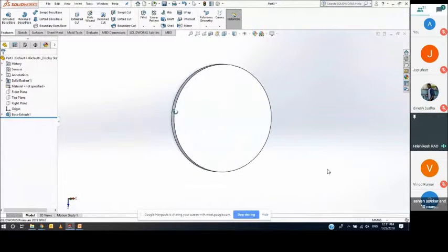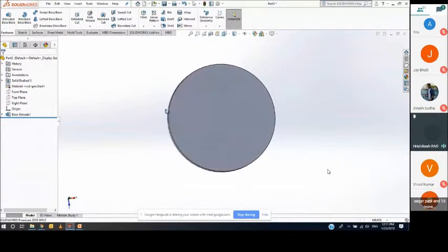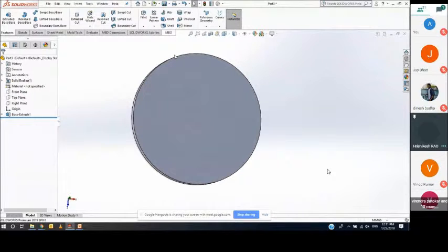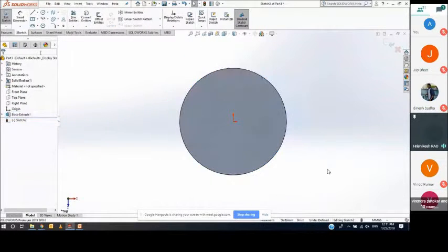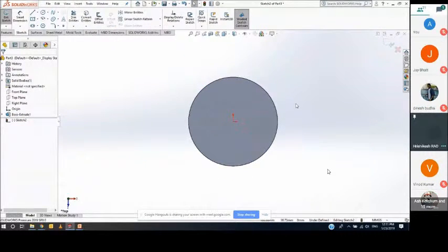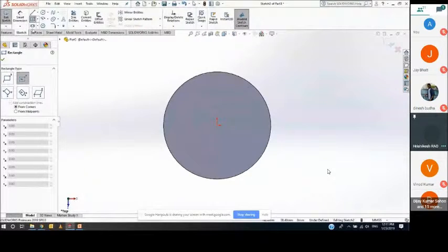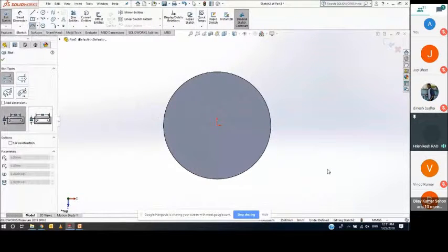And I just want to create some holes on this circular boss. So for pattern, I'll just create a parent, the type of hole that I want. For example, I just want a simple, say, straight slot. Just create this slot at the origin itself.